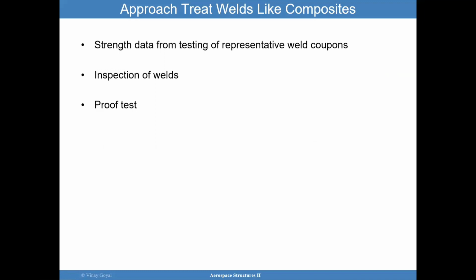You can inspect the welds. You can learn how to better inspect them in the field, such as the ultrasonic inspections we talked about, eddy current, or any of the other techniques like X-ray, and leverage them to develop acceptance criteria for the welds, where you can put flaws in on purpose or crack the welds on purpose. Tie that to an acceptance criterion with an inspection, and then make sure that when you go to the field and apply that inspection, you can repeat the acceptance criteria and judge it against your qualification program, which could be made of hundreds of coupons.